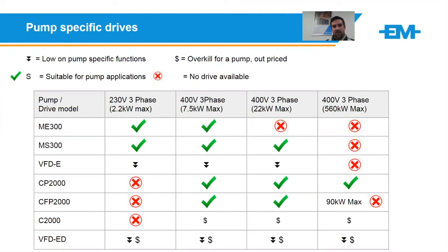So I would say 60 to 70% of the pump houses are probably run by generators. There are some tricks. Some generators might not like the non-linear load of the drive. I would just confirm that with the generator supplier. There's a lot of literature on the internet about running generators from drives, but it's definitely possible and something we do quite often.